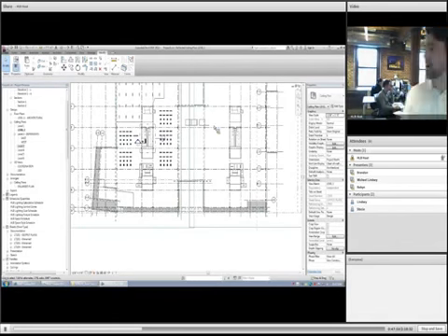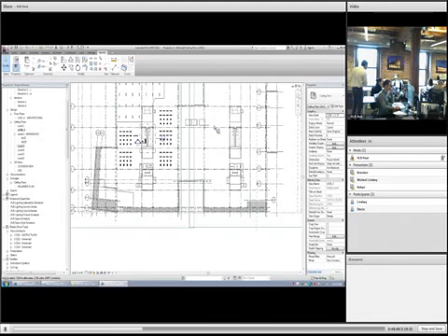That's the funny thing. Copy in Revit is different. Copy clip, I should be saying, is the correct terminology. Do a control C, and then hit escape, and then on your modify tab, paste, pull down, align to selected levels.